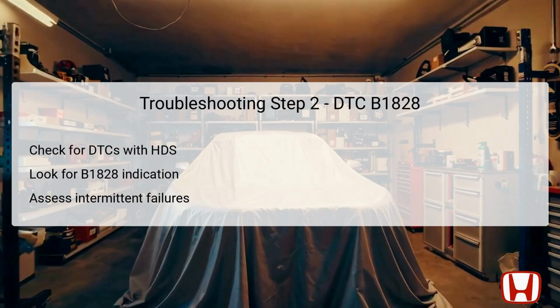In the second troubleshooting step, using the Honda Diagnostic System, HDS, check for any stored DTCs once more. This step aims to confirm whether DTC B1828 is still present after the clearing process done in Step 1. Assessing whether this code is indicated will determine the next actions. If B1828 is indicated again, it signifies a persistent issue that requires further investigation. Conversely, if the code does not reappear, it suggests that the initial failure may have been intermittent, which indicates that the system could be functioning correctly at the present moment.